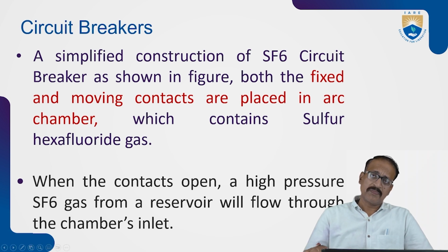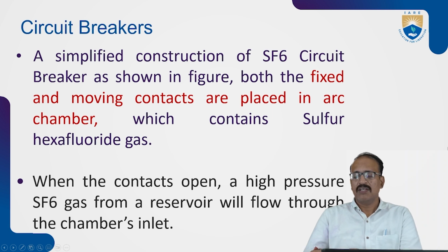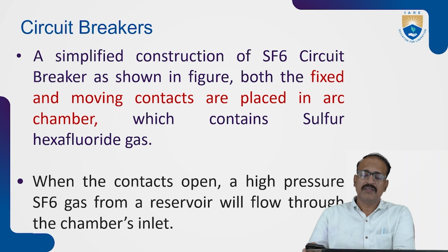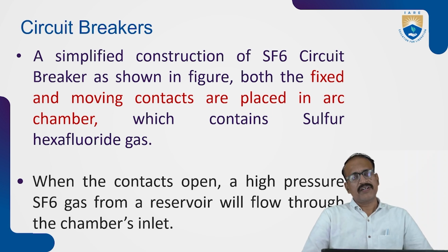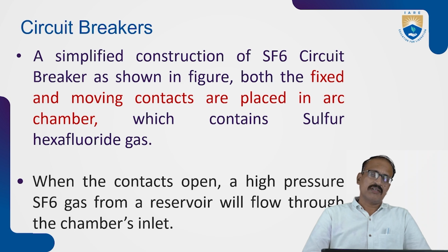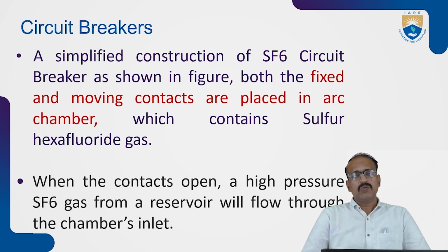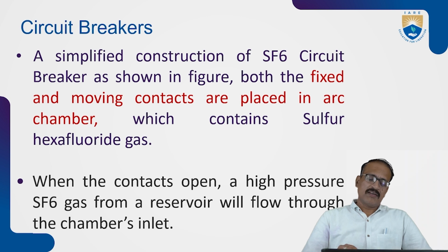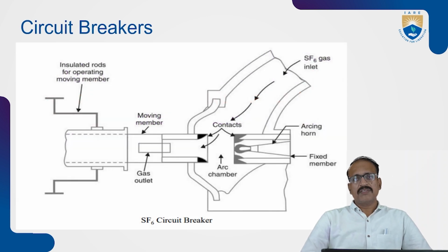For the best performance, we are constantly searching for alternatives, always trying for betterment. Since sulfur hexafluoride is electronegative in nature, it has the best performance: it absorbs the electrons, so it stops the conducting, and indirectly it will extinguish the arc as early as possible.